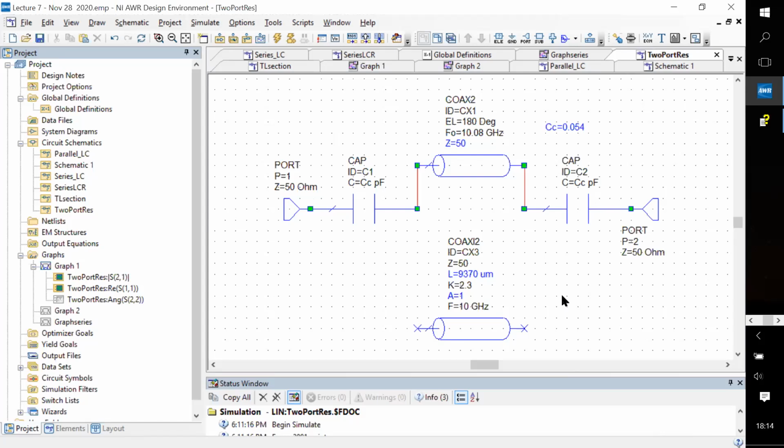For the symmetric one, the S21 or S11, the quality factor will be the same, right? Well, there is only one resonator, and as long as you measure the quality factor correctly, which means that you use the correct measure for the transmitted signal if you're using the transmitted signal, and the correct measure for the reflected signal if that's what you're using, they will of course have to give you the same answer. Because there's only one resonator here.